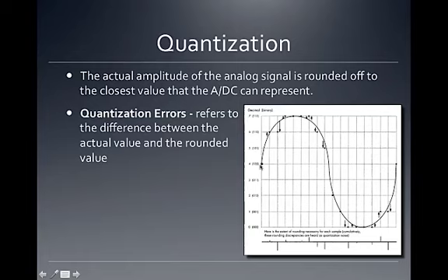But the problem is that when we try to quantize that, this sample right here, when we try to assign a value, it gets caught in between. It's either going to quantize to this number or this number. It can't be right in the middle because there's literally no bit to represent that. So what happens is that we get this kind of tick, and you can see down here, these tiny little ticks and pops are these quantization errors where it has to round off because the bit depth isn't high enough to represent the audio.